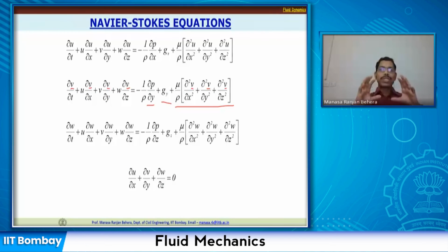So the Navier-Stokes equation has been derived to solve fluid flow problems. You see here we have considered the body force, the pressure force, and the viscous force. To note it down, the Navier-Stokes equation considers the viscous effect of the fluid. And the moment we say the fluid is viscous, we are basically saying the fluid is a real fluid.